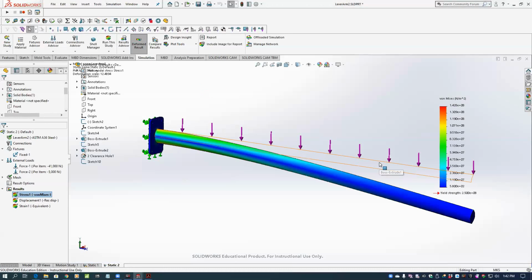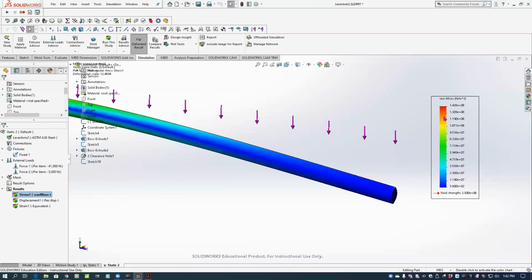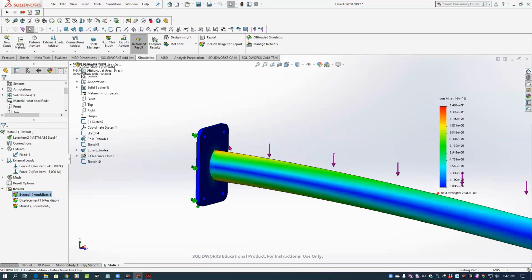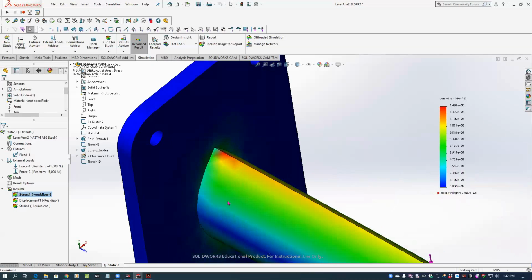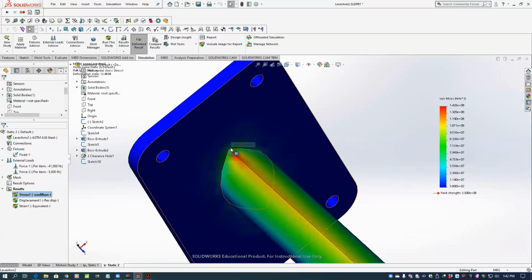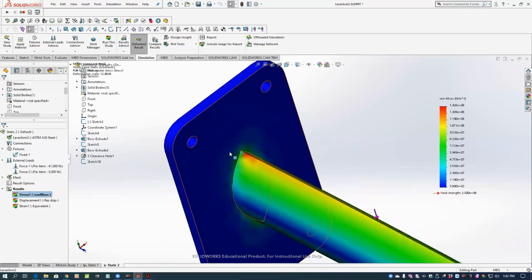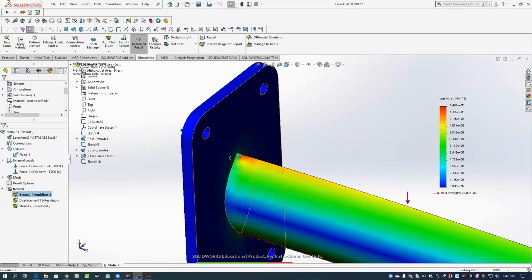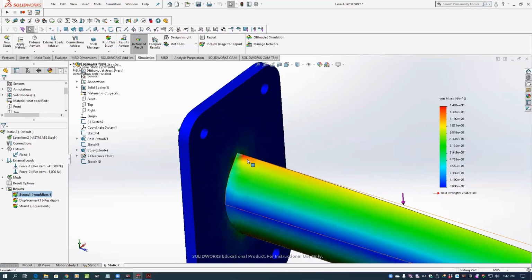And we get our maximum stresses here, the von Mises stresses, newtons per meter square is Pascal. This is times 10 to the 8th. So we do have a stress riser here where the sharp corner there interacts with this plate or with our restraint, and it would be the case whether we have the plate there or not, but where it's restrained.